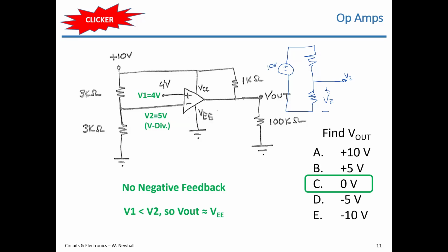And someone asks, how do we know it's a comparator and not an inverting comparator? You don't really have to know what this circuit is called. All comparator circuits that you'll see will do this. V1 is always, in our class, the node voltage at the non-inverting input. V2 is always the node voltage at the inverting input. If V1 is greater than V2, the output is VCC. If V1 is less than V2, like it is here, the output is VEE. Okay.